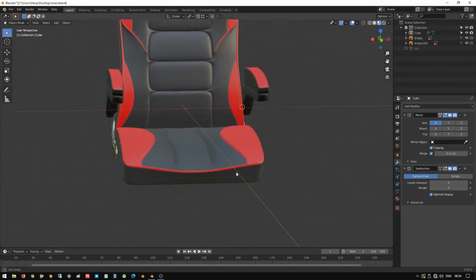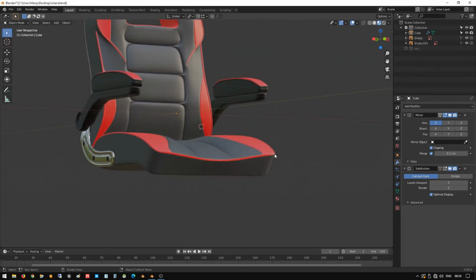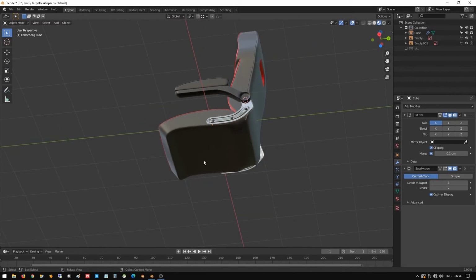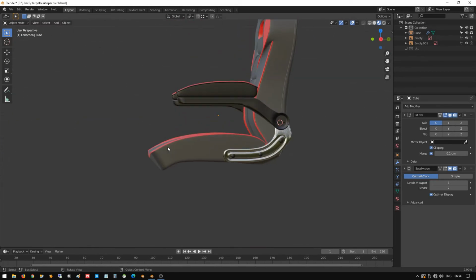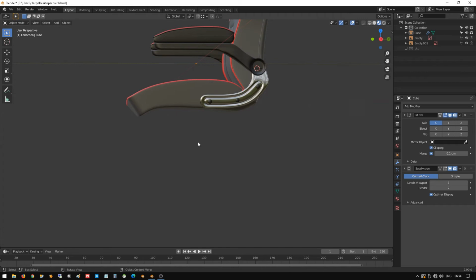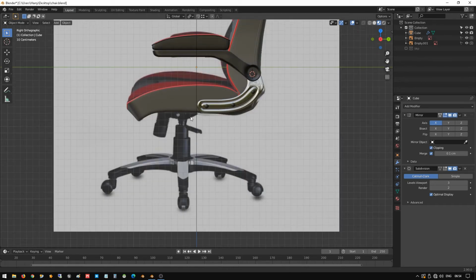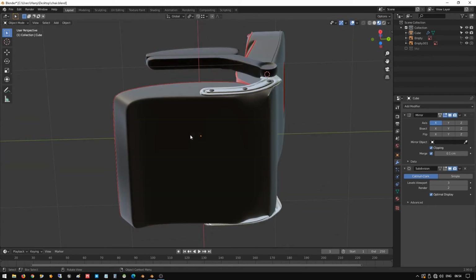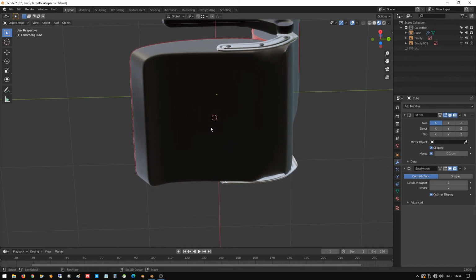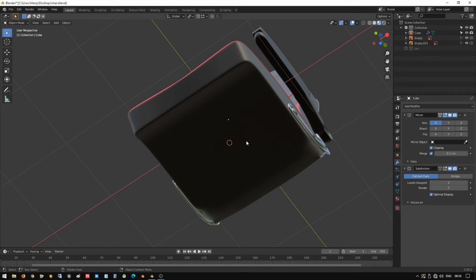Okay, now we have cut it in the curve shape. Fine, now this is finished. Let me go to the bottom view. Go to the bottom and Shift right click to create a 3D cursor in that particular area.